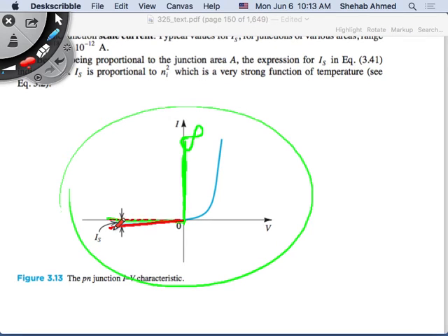So the saturation current increases in the reverse bias, let's say linearly, but it's a very small value. Then, in the forward bias region, I have a voltage beyond which current will increase significantly. Right? And that, we said, is around 0.7 volts, and we called it the forward voltage.